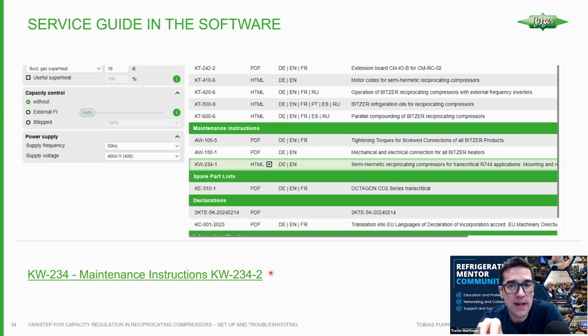So if a technician's phone is dead, what are maybe 3 or 4 things that they can check on one of these compressors to really let them know what's going on? For example, these are unloading compressors. When you're at 100% capacity and you're checking the amps, they are going to be the highest, depending on your suction and your discharge conditions. But when it unloads, all of a sudden you're going to notice those amps drop off. There's no linear relationship with this because it all depends on the conditions of your suction and your discharge.